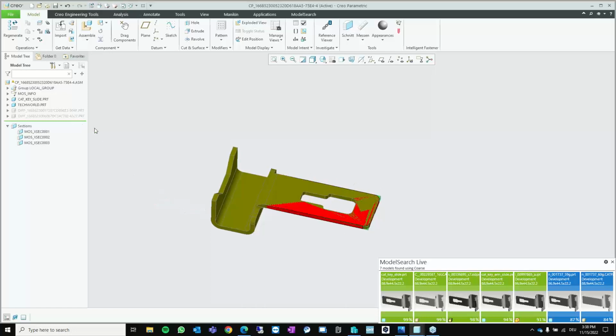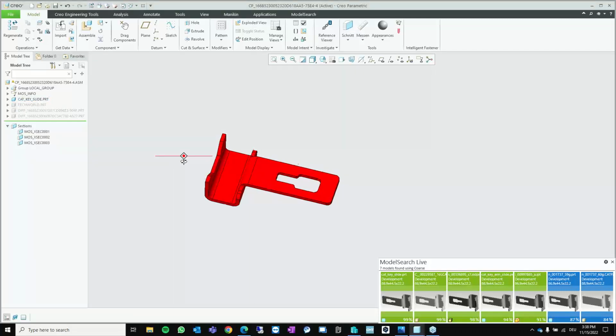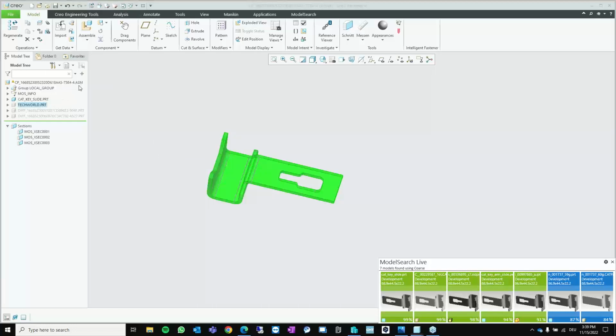When looking into the model tree, maybe somebody has already recognized 2 additional models which are hidden by default. They are our so-called difference parts. And let's talk about how they are created. It's very easily explained. In the first one, we copy geometry from the red one, from the one that's located at the top, and we subtract geometry from the second one.